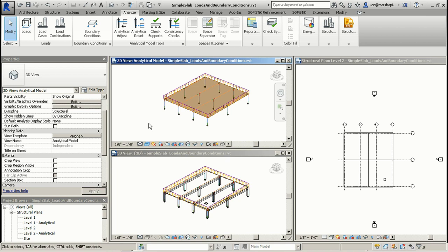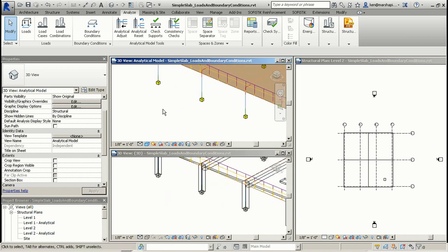I've put all of these yellow, you can barely see that on this. Let me zoom in a little bit. All of these yellow are boundary conditions. If there's a footing that gets inserted, the footing analytical model in Revit is literally a point. It's just an XYZ location. It has some data associated with it so that analysis packages could read that out, but it's just a point at this point. You could assign that boundary condition to the foundation if you wanted to, but they wind up coincident at the same point, and most analysis packages would just take it as the bottom of the column anyway.